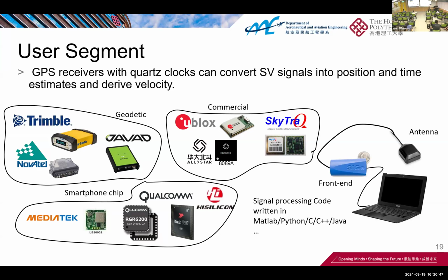So for example, if you want to really do the positioning, first you need antennas, right? You can put the antennas outside the windows to collect the satellite measurements. Then you need a front end. The front end does the signal acquisition and tracking. It transfers the radio signal from the satellite into physically understandable measurements, I mean the range, the distance from satellite to receiver. Finally, those data will be processed with a computer or microelectronics to calculate your position.